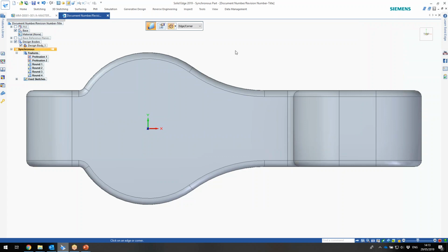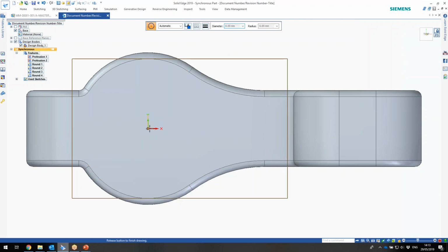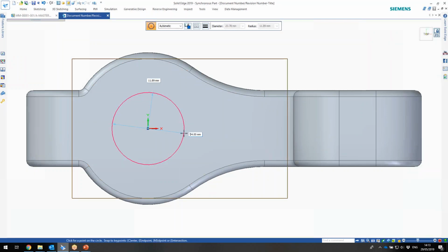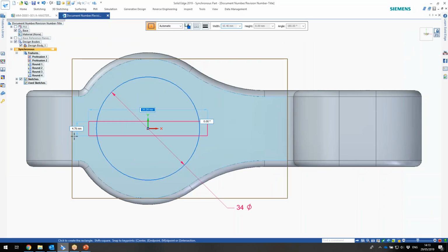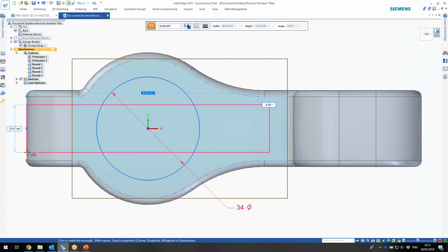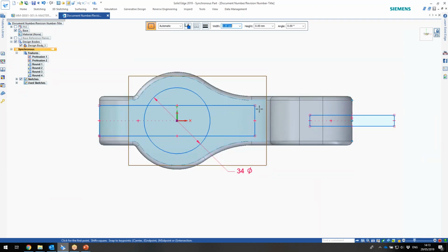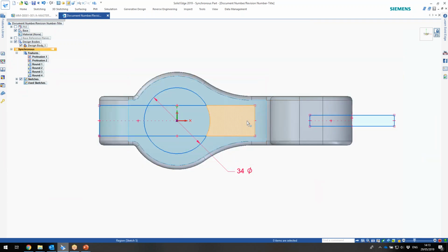pillar hole and slot. So again, similar to the other times, the padlock comes up, we're going to lock on that face, create the hole, and then create the slot. And we're going to create another slot over here. Now I'm going to make these slightly different sizes because I want to show you 3D face relationships and how that can speed up your design. Because as we make edits later on, it's really important.